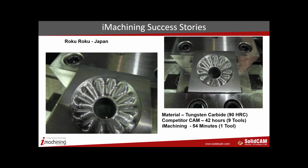It gets better and better as the material becomes harder and harder and the tool becomes smaller and smaller. You have got to be extremely right about selecting the right cutting tools. Your cooling design has to be near perfect. I've shown you one of the designs. You could have several designs, but the goal is to hit every point of the tool with extremely high force of coolant.